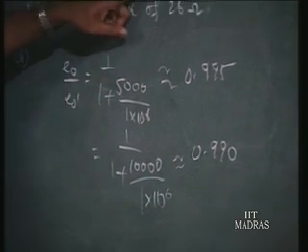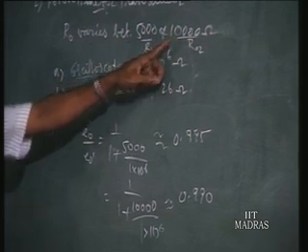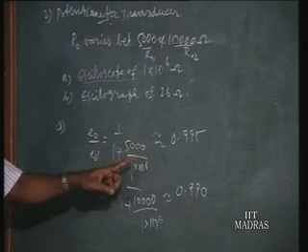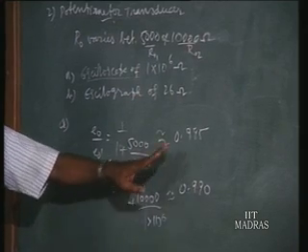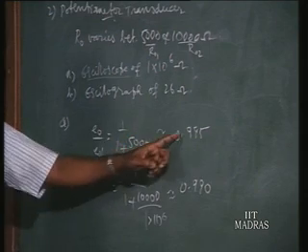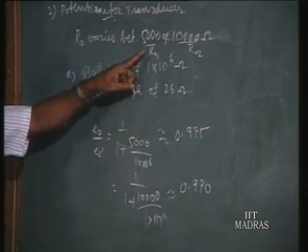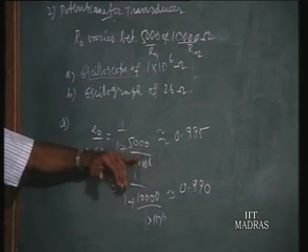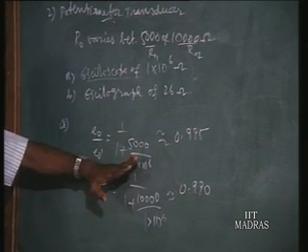Now here we have to learn one point. Since the input impedance is of the order of 1 mega ohm and the output resistance is only a few thousands of ohm, though the loading effect is varying, the ratio is near about 1 only. That means EO will be very near to EO dash. It is because the input impedance is very, very large, 10 to the power 6. We want only 10 times more, but here it is 100 times and more.